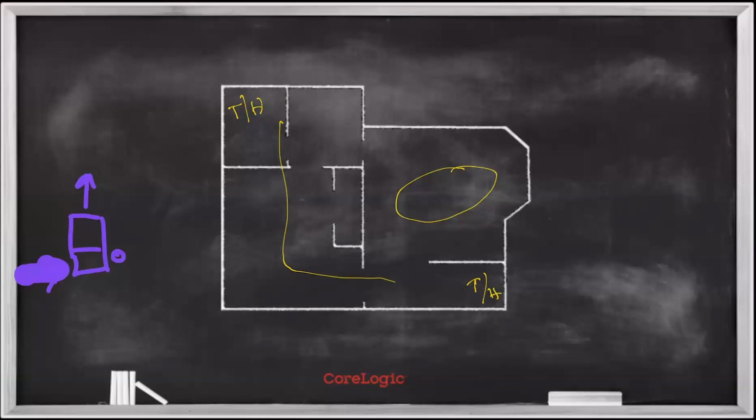Now, because of that, that air mover has to be installed in a very specific direction: the intake drawing from one room and the outlet dropping into the next. You see the direction of flow there? The intake coming from one side and the outlet going into the next. That orientation only works clockwise. When you install your air movement, start around the perimeter of the room and move your air in a clockwise orientation.